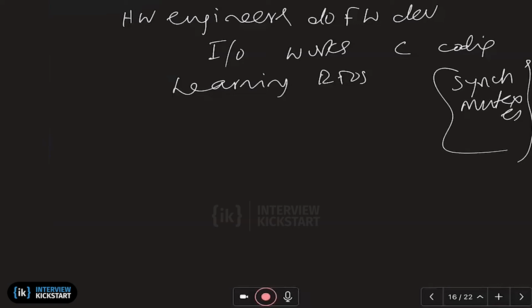The technical advantages of an RTOS are primarily separation of concerns and abstraction, but there is overhead. Those are also technical concerns. Cost is a business concern in terms of choice of components, licensing cost for the RTOS, tools, maybe even tools. So when you're debugging with the RTOS and without the RTOS, things can be different. So debugging tools, right?